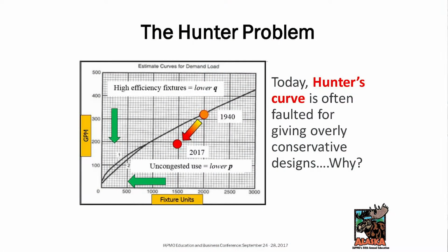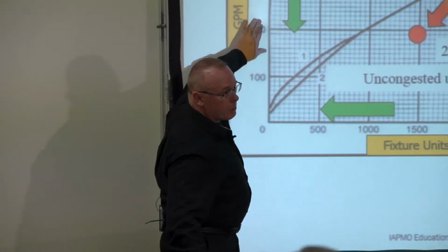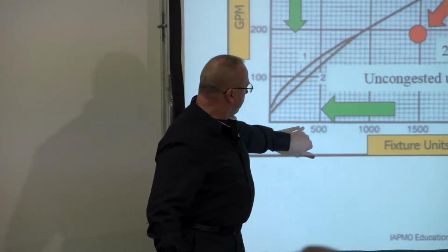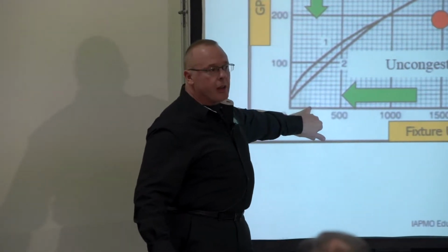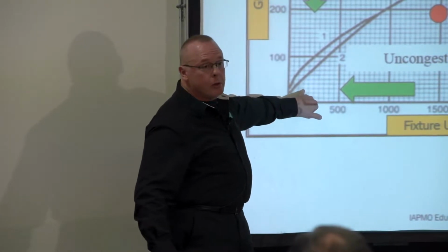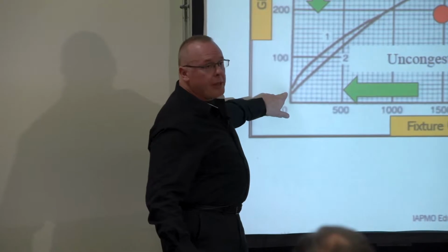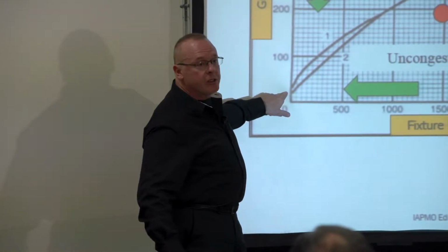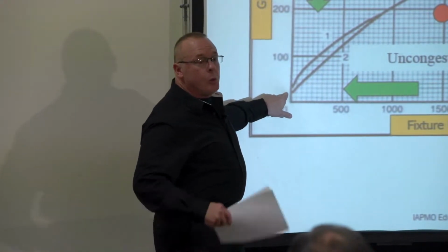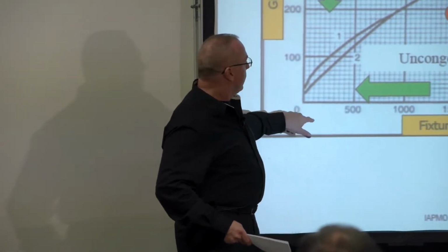These are like the number of fixtures. And here, take away the gallons per minute, and this is also numbers. And so he would plot 6 out of a total number of toilets, 6, and then 2. And then he would come over, and then he would multiply 2 by the gallons per minute. So you wouldn't size the system for all 6, you would size it for 2.